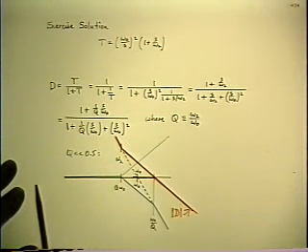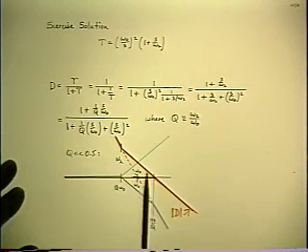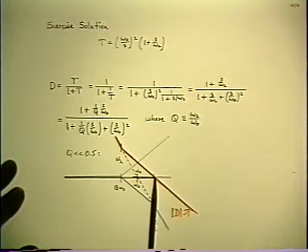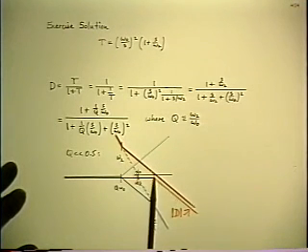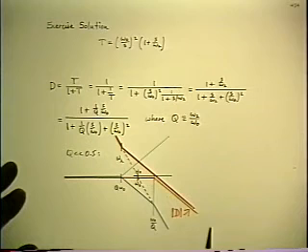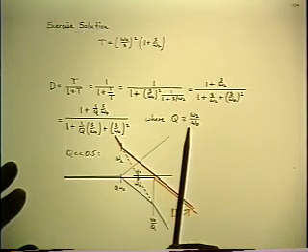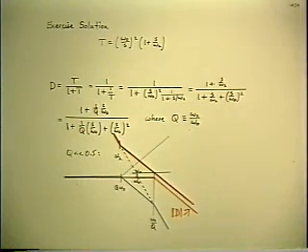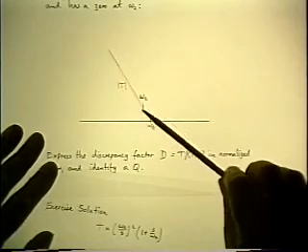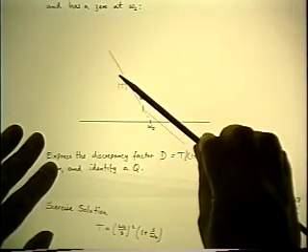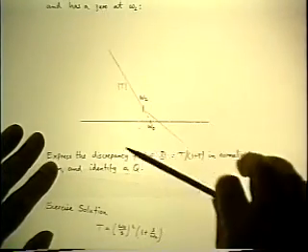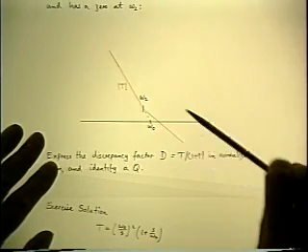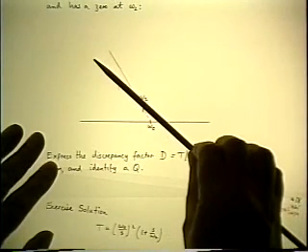And the closed loop gain simply stays flat until the single slope crosses over, and then the closed loop gain follows the T. In other words, as long as Q is low enough to justify the real roots, that is, as long as the omega 2 is low enough down here, the double slope part of it isn't doing anything. And you're back to essentially just crossing over on the single slope, which is the ideal reference case.